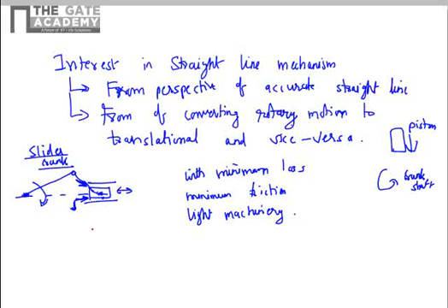There are two components. We will be studying these forces in the analysis of a slider crank mechanism in much more detail in coming lectures. But I am just giving you a brief idea that there will be a compression in the connecting rod and you will get a lateral thrust. To balance the lateral thrust, you need to have some kind of robust arrangement to take that friction. Because of that normal force, some friction comes, so you have to do some good lubrication and take the lateral thrust.